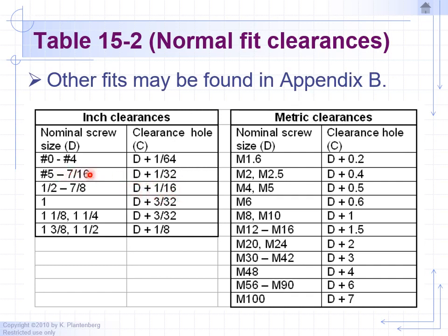And if you're dealing with smaller diameters, we're going to go with 1/32. So 1/32 is about the thickness of a credit card. Okay, so take whatever diameter you're using from this range, and your clearance hole will be that diameter of the bolt plus 1/32, which is about 30 thousandths, 0.03125 to be exact, and that's about the thickness of a credit card. And for metric, we use this table.